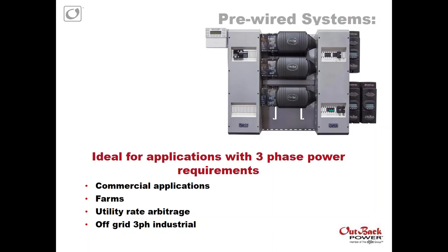As well, these systems can be stacked up to 3 of them in series, for a total output of a little over 30 kilowatts. You can go up to 32.4. Another little piece there is that these do handle about double the surge. So you can go to 65 kilowatts on your actual surge requirements, depending on what equipment you may have hooked up to these things.